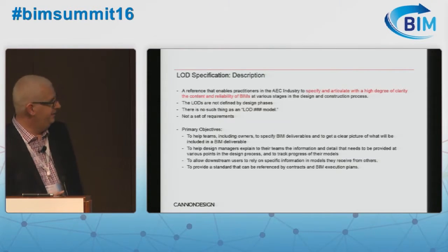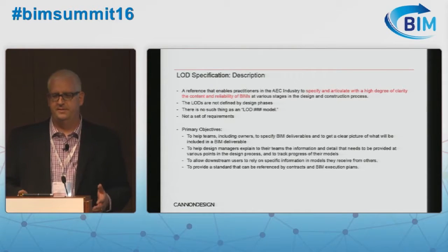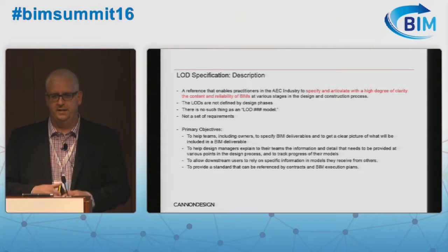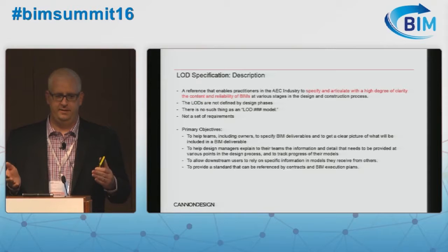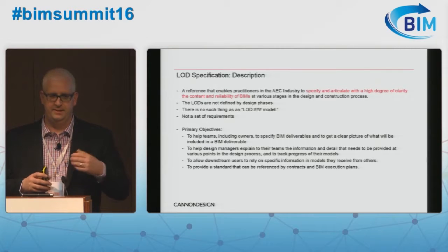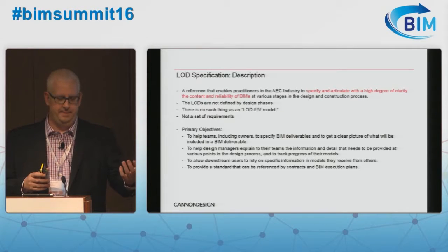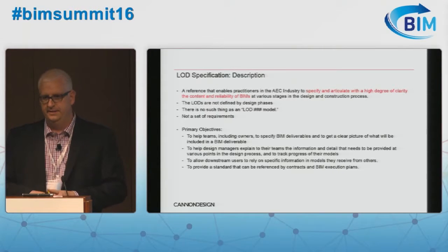The idea of LOD is, again, we've talked about not being a set of requirements, and it's not something that's specific to a design phase. The LOD talks about how these individual elements progress. The idea of these elements are based on the Uniformat classification, so they're building assemblies. It's an exterior wall assembly. It's an interior wall assembly. It's a mechanical air supply system. It's a storm sanitary line that's in the building.